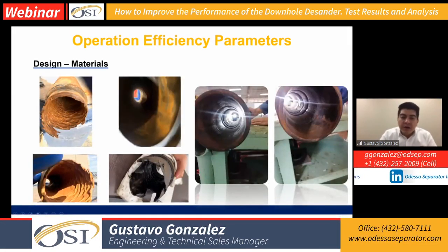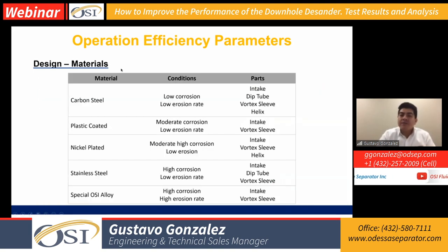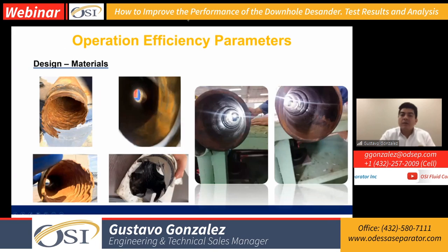In these other photos, we're going to see more severe cases where we actually cut the thread connection. In this case, the internal portion of the sleeve, we see everything in good shape. There was no damage through the system, so the sleeve didn't have a severe mark, just at the end.